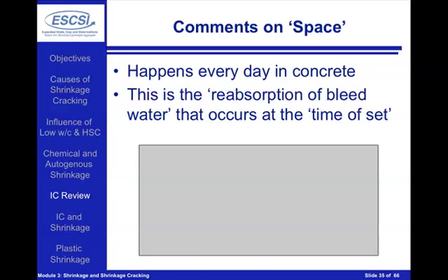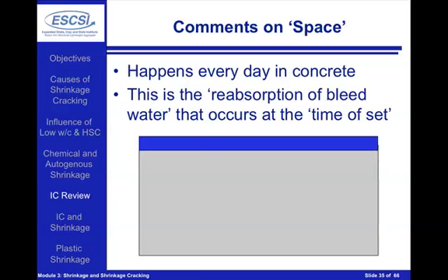Now you may say all this sounds like something I don't see in my normal concrete, but I want to take a step back and say that this happens every single day inside of concrete. Many people notice that bleed water can come to the surface of concrete. Actually, what's happening is all the other particles are sinking down, and the water is not sinking as fast as everything else, and that's forming the sheen on the top surface. The interesting part of this is we know that when the water sheen goes away, this is correlated to the time that the concrete starts to set.